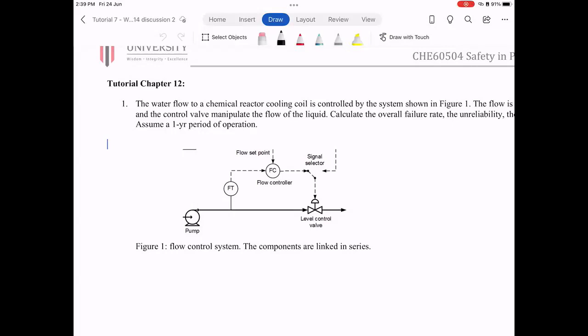But in reality, we will avoid designing a pump followed by a control valve, because every time we throttle the control valve, we actually throttle the pump. Most of the time the pump comes in, the flow goes through a certain process, and the valve comes before or after, most of the time after, unless the control valve is an on-off valve to let the flow go or not go.